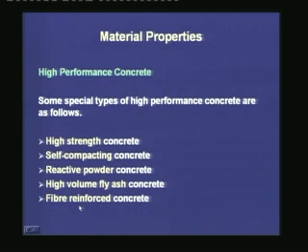In this type of concrete, small fibers, either carbon or graphite, or the more popular one, steel fibers, are poured into the concrete during its casting. The benefit of fiber reinforced concrete is that it reduces the shrinkage cracks, and since the fibers are oriented randomly, it can also be used for a region which is subjected to stress concentration and tensile stresses.